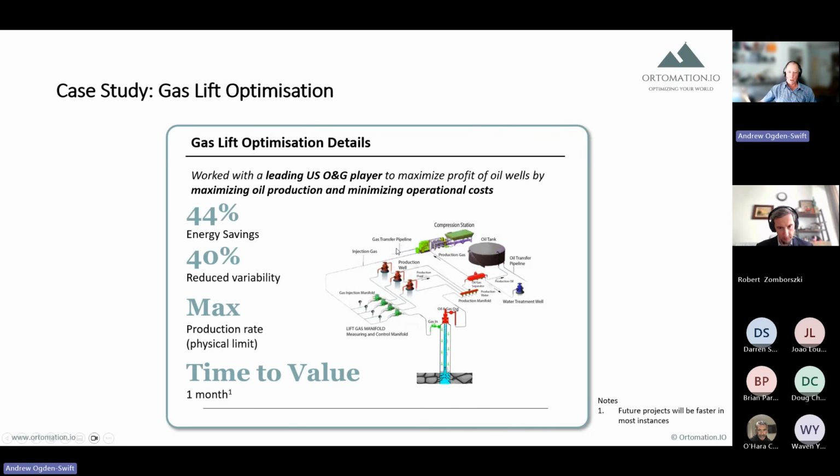The rest of the gas is then transferred to a gas pipeline. And so we applied auto agents to 5 gas lift flow controllers on 5 wells over a period of several weeks. There was a roughly 44% reduction in gas flow round this circuit, going round here and back to the compressor, therefore saving energy use.